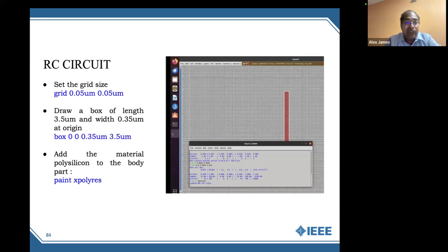Then in Magic, if you want to have a capacitor and a resistor, then we have to start drawing those components. There is a particular value one needs to estimate for the capacitor and the resistor, because in analog, these blocks may not be automatically there for the layout. You need to draw it. So you can go about estimating the size: for capacitance, what would the capacitance be? You basically calculate that with the equation. Then same thing with the resistor.